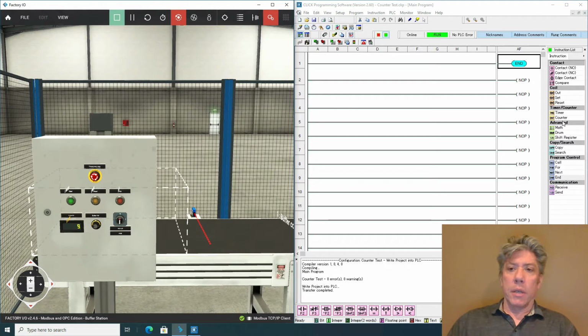But anyway, there's clocks running because you've already got a clock signal, a pulse signal, that drives the digital logic, the processor and the memory and so forth. So you may as well count those clock pulses to determine how much time has elapsed. So you can use this for timers and counters. It's not something you have to worry about as the programmer. It's just a function essentially that's included with the PLC. We'll start off talking about counters, but there's a lot of similarities between the two, and there's a few differences.